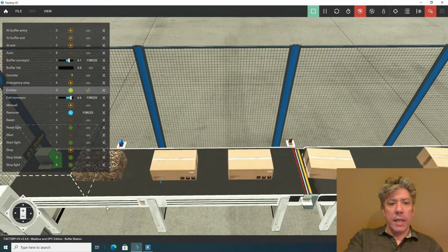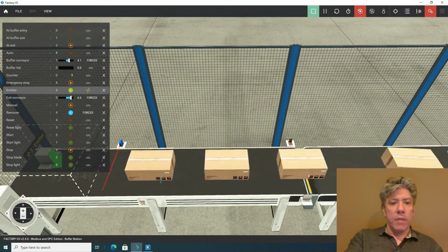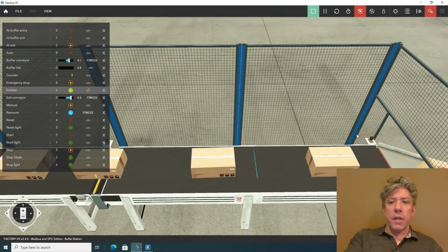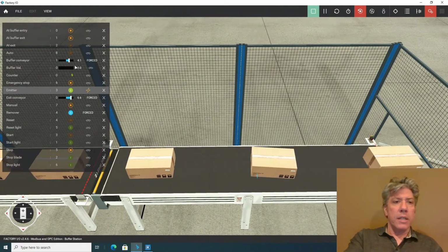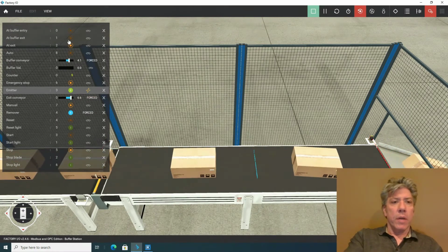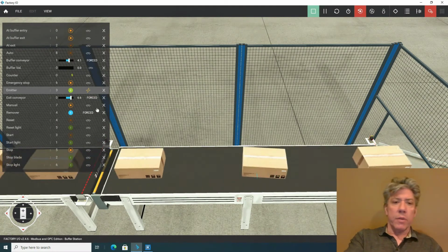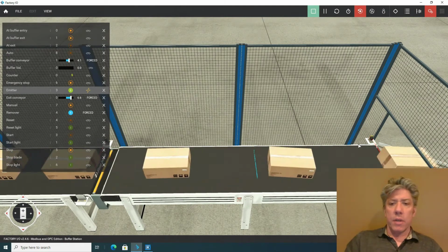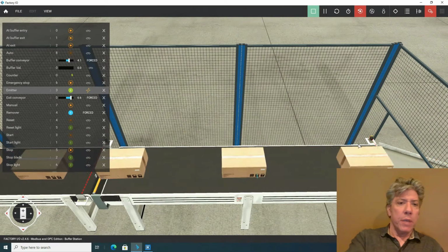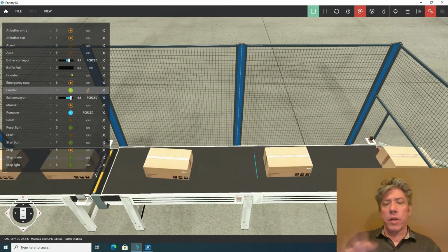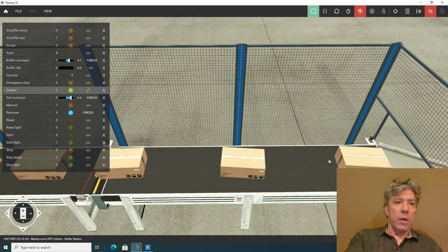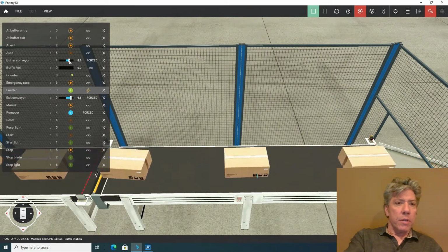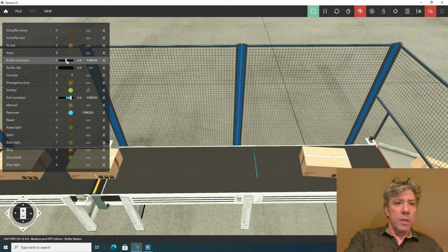And then at the exit, which is all the way at the end of the exit conveyor, you'll notice that there's yet another sensor to sense boxes leaving the system. Okay, so that is turning on and off as well. All of these sensors are on-off. They're Boolean type things. They're binary, whereas the conveyor speeds, for example, are outputs that are continuous outputs instead of on-off type outputs. So I'm going to shut off the conveyors and reset the simulation.